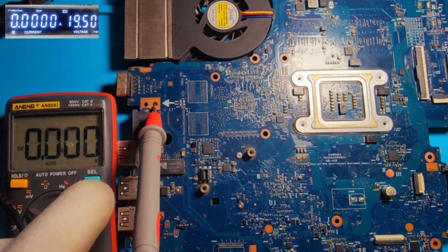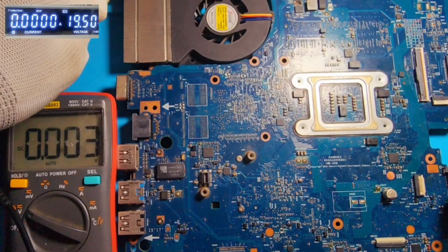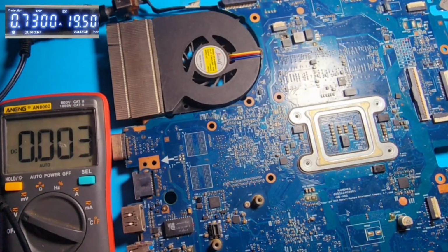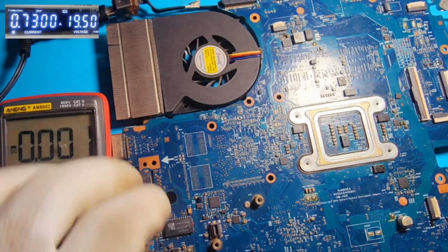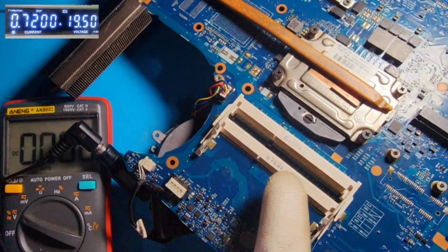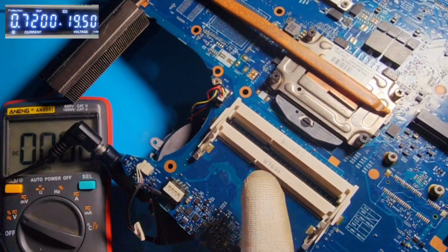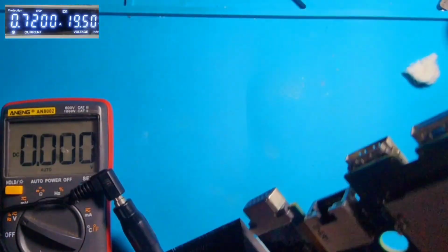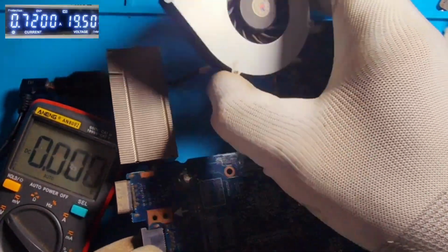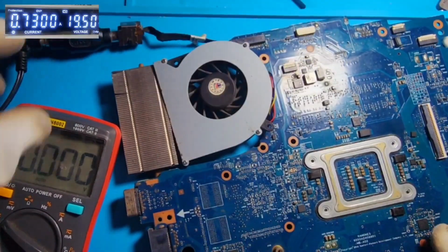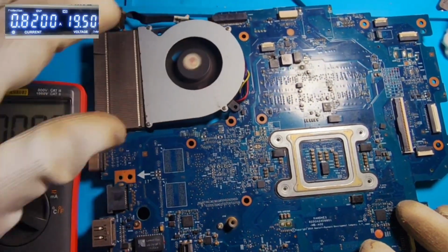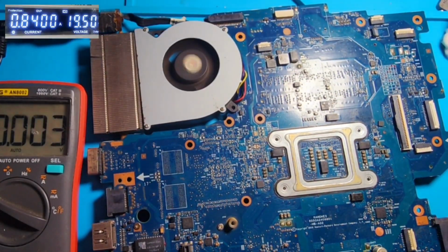Now the display of the power supply is visible to you. Now I am going to connect the adapter. We have not connected the RAM module in the board, so we may not get any high current reading. Anyway, we can check the voltage at the system data line, whether we are getting 3.3 volt in its place.